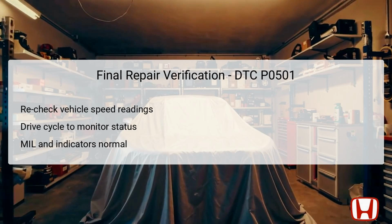During this drive cycle, monitor the status of the malfunction indicator lamp, or MIL, and ensure that it remains off, along with the shift position indicator returning to normal operation. It's vital to confirm that there are no returned DTCs or pending codes, ensuring that the system is functioning properly without any lingering issues. This comprehensive verification provides assurance that the repairs have addressed the initial concern.